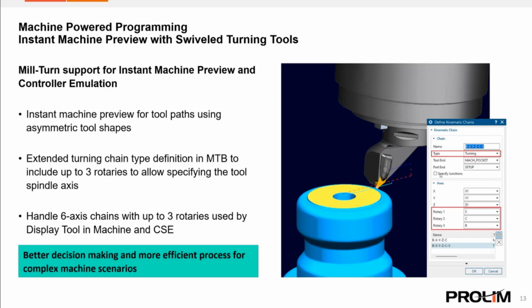So implementing support for auxiliary axes is a stepping stone to covering multi-axis machine types like mill turns. It is the next step to provide the means for the user to define kinematic chains. So the kinematic chain specification and the support for swivel turning tools will extend the supported use cases for pick on path with machine under the umbrella of auxiliary axes.